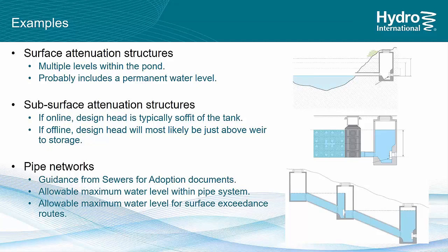Therefore, you would use above ground areas or maybe the roadway for your larger storms, where appropriate, to not flood people's houses or cause danger to life. Maybe having a design head that's above cover level might be appropriate to control the amount of flow going through the system and make use of the topography above ground.